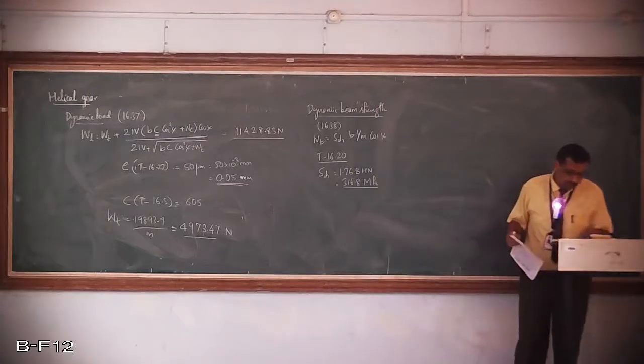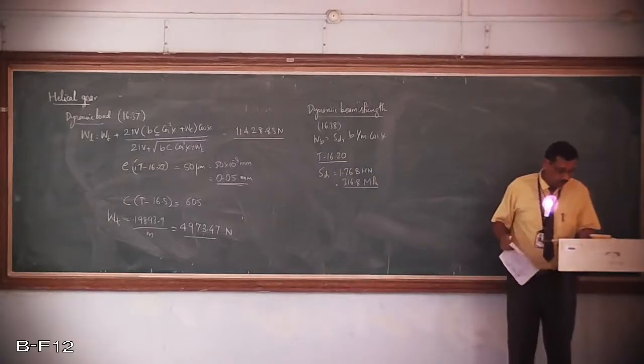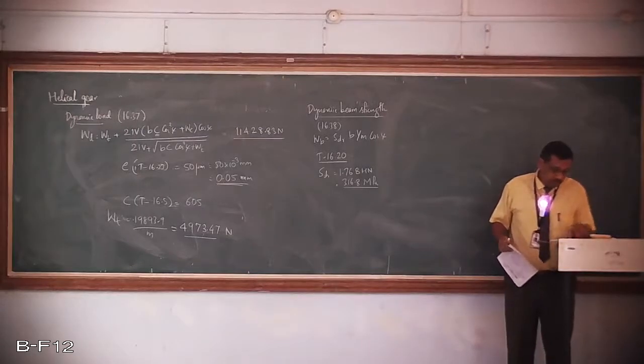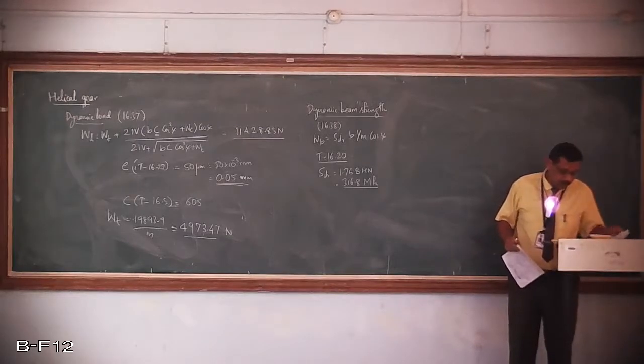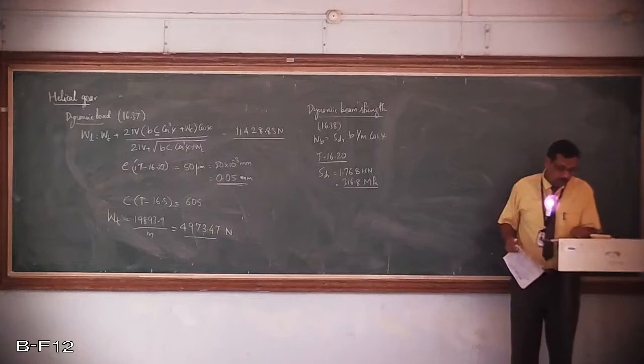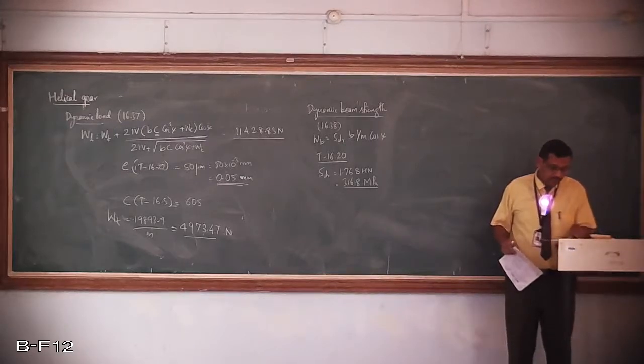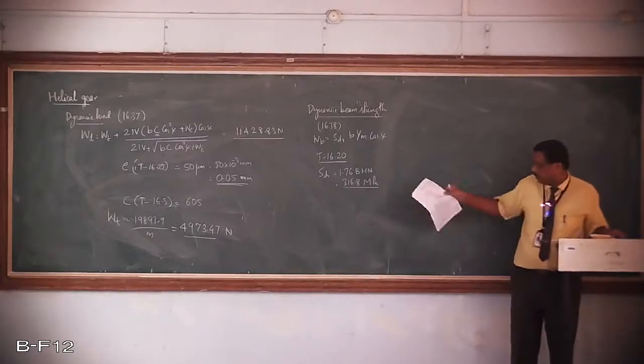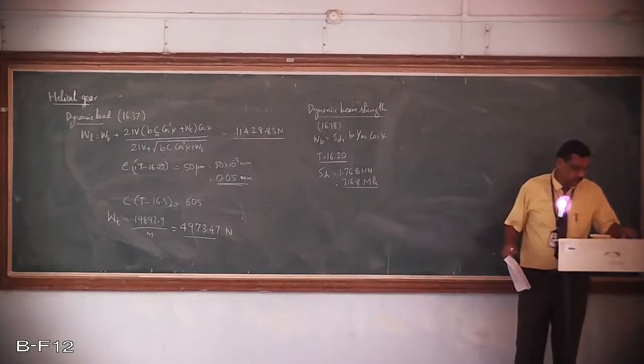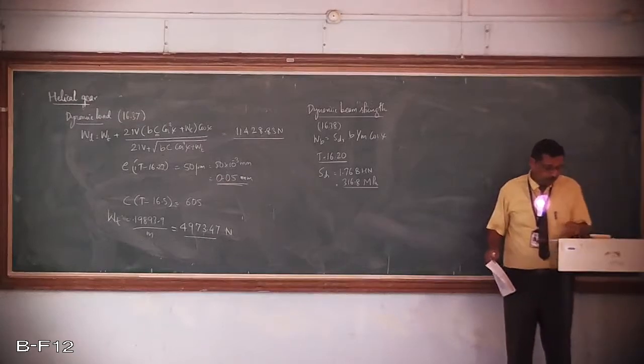This is for the steel that is given, or SN equal to 700 megapascal, or the value is given between this and this, based on the hardness. If you see, the minimum hardness is 180. For the helical gears, SCN endurance limit is 175 to 195 megapascal, whereas here we get 316.8. We'll go with 316.8, making use of that equation.